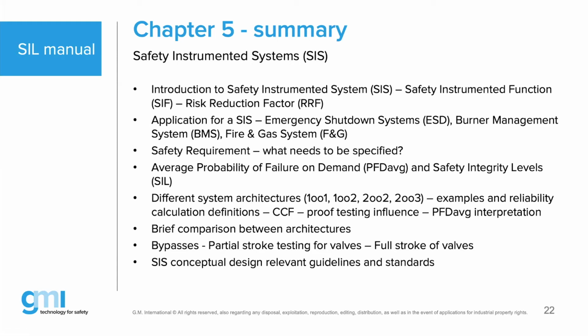Then we have the average probability of failure on demand. That's the PFD with the SIL levels. Different system architectures. And I saw in the registration, there was someone talking about voting degradation. Well, clearly in your safety instrumented system, mainly in your safety requirement specification, that is where you will have to write down for the end user, the instrument engineer or the maintenance engineer: if you have a 2 out of 3, how do you degrade to a 1 out of 2?